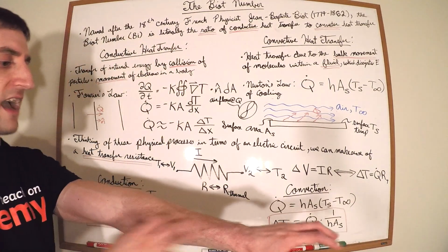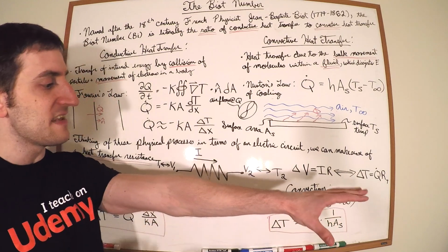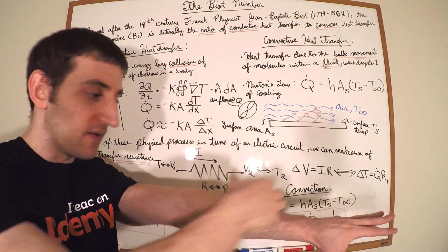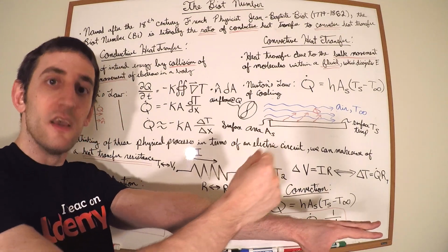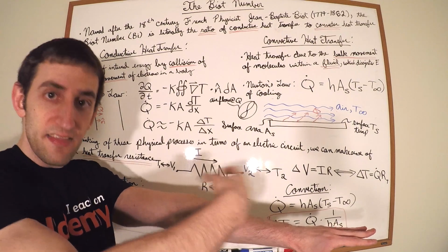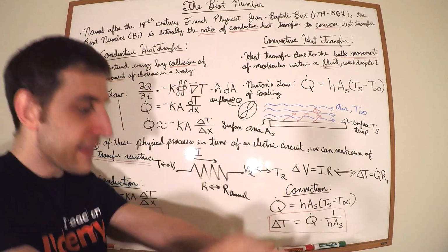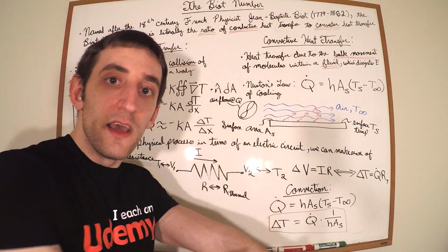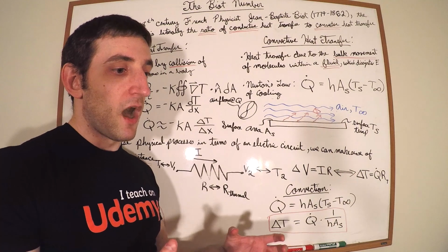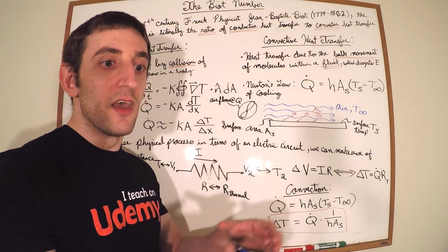Natural convection is the fact that if you have some hot object here, natural convection states that the air molecules close to that surface are going to take that energy, right, because they're butted up against the surface, they're going to take that energy, it's going to get transferred to the air molecules, it's going to get less dense, and then it's going to rise due to that density gradient, if you will. So we know that more dense objects tend to sink.